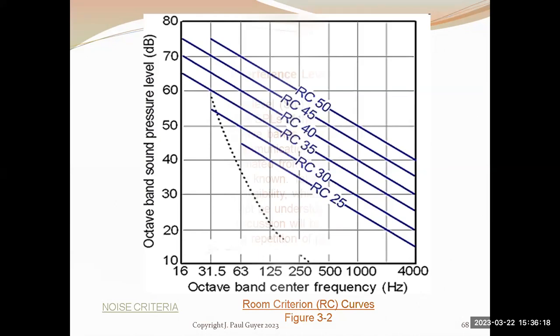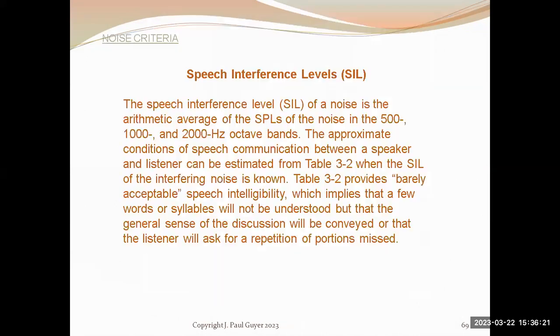Speech interference level is the arithmetic average of the sound power levels of the noise in the 500, 1000, and 2000 hertz bands.